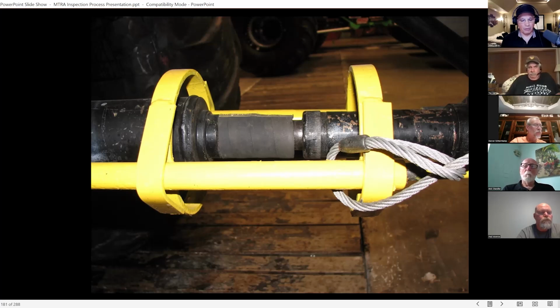And we've seen cases where guys will put them together and forget to put it on. So what they'll do is cut one and put it on with tie wraps. No, that won't work. It's got to be a solid piece. Also in this picture, you can see a cable restraint on that loop. Again, some places require that. They want those tethered. I've got that further down in the presentation. Okay.